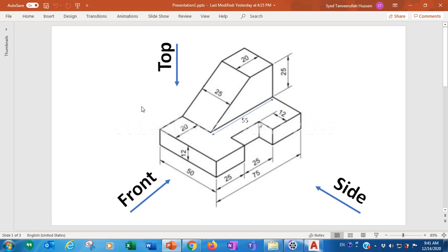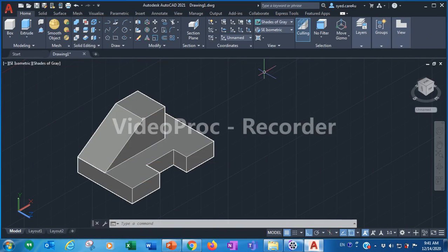So in order to move it again further to the corner, this corner must be visible. This corner is not visible in the right side view, but it can be visible in the left side view. So we have to go to the left side view. The overall view must be changed in order to look at this. So go here and select left side view.